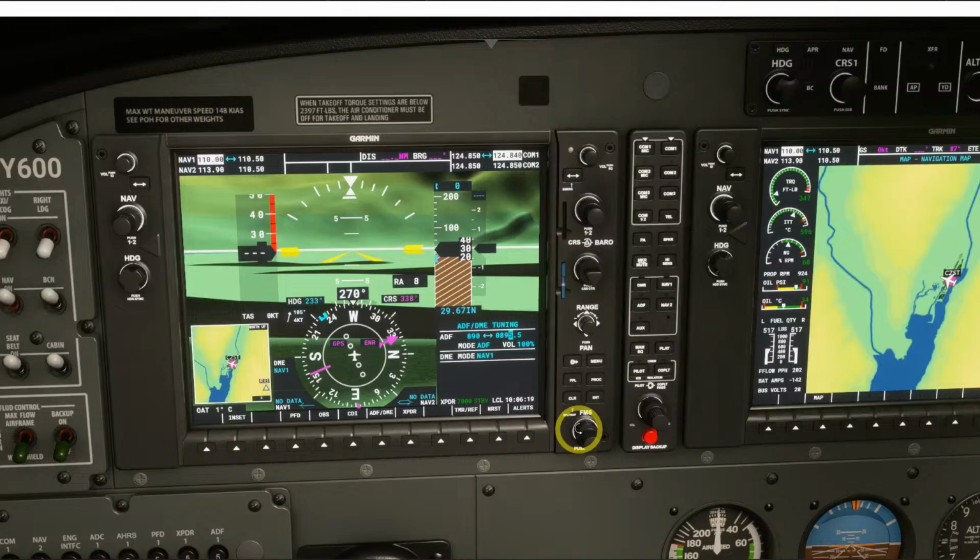Outside knob switches to the hundreds and thousands and whatnot. You adjust whatever you want. Once you are happy with the selection, you hit enter. It will warn you, is this what you want to do? Enter to transfer again, and you press enter again, and it activates. Okay. That's the ADF. To exit from this screen, you click on the ADF again, it will disappear.